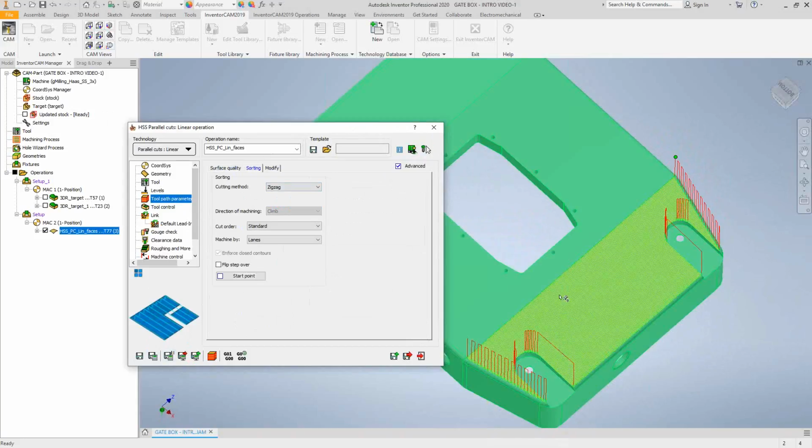So obviously, as it zigzags back and forth, these little movements over here, it just links them, and it just continues on. So it looks like a smoother looking toolpath, but just be aware that because it's zigzag, it's alternating between climb and conventional. But what we're seeing on the edges here is some link between slices, because it's getting to the end of those surfaces there. And some of these are actually gaps along cut because of the fact that as it's zigzagging, the next pass is actually right over there.